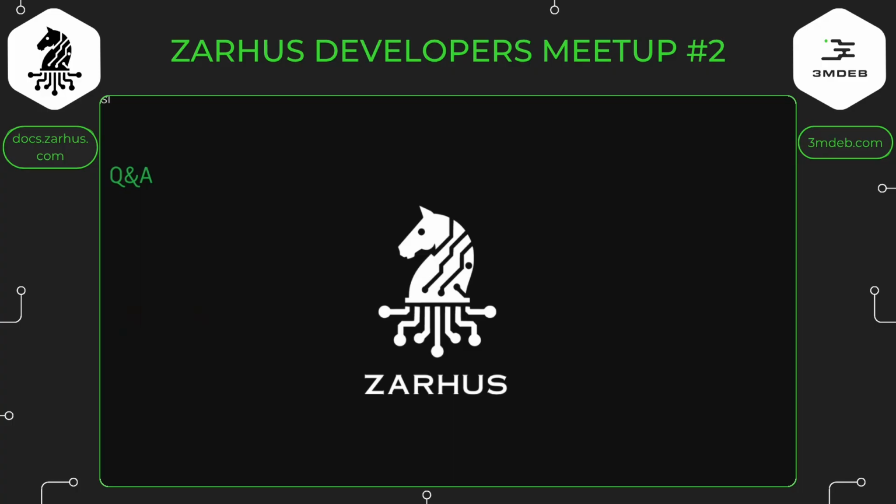It's a simple interface in which both host and the BMC are able to control the hardware features of the platform. It should be noted that this is the physical interface, and the protocol that we will be using to talk from BMC to the host is called IPMI. So KCS is a physical interface.